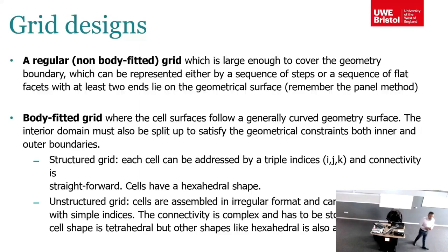But in a body-fitted grid, you should know whether you want to use a structured grid or unstructured grid. With structured grids you get better convergence. With unstructured grids you can have convergence problems, but you can have smaller grid cells and penetrate everywhere in the body. So with complex bodies, unstructured grids are easier to deal with.